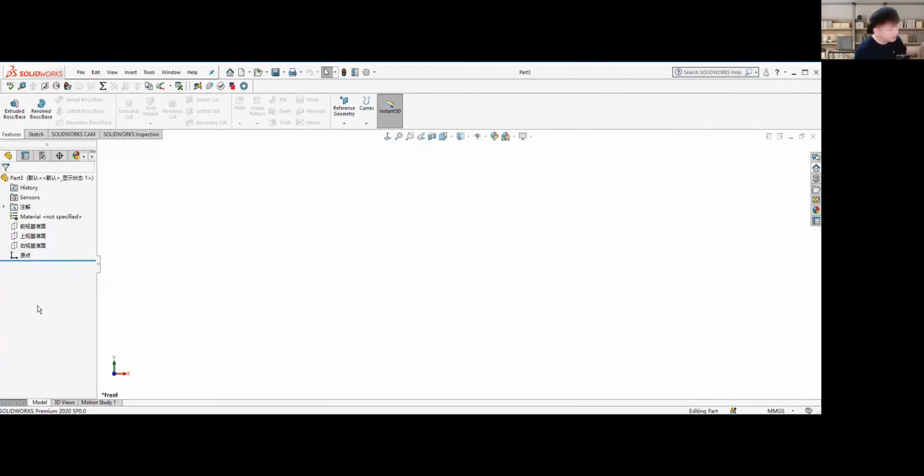Now I want to design this bottle. It's not a bottle, it's a glass, how we drink. See, it's empty right here. It's not like the camera, where we built an extrude on it. It's empty here, so we need to use the extruded cut option.